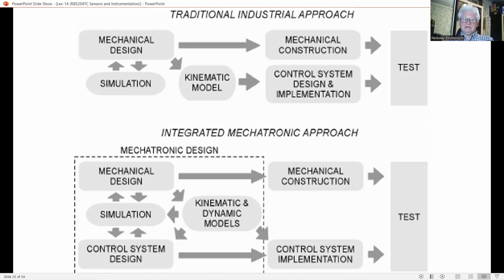When independently designed components are interconnected, several problems arise. First of all, when two independently designed components are interconnected, the original characteristics and operating conditions of the two components will change due to loading or dynamic interaction.